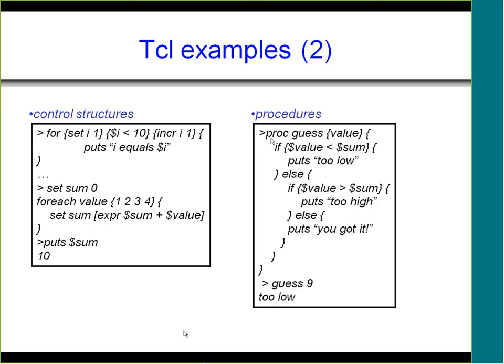Next, I want to show you the syntax for how to define procedures. In Tcl, the command for creating procedures is proc, followed by the name of that procedure, and followed by all the input values that are going to be used inside of the body of the procedure.